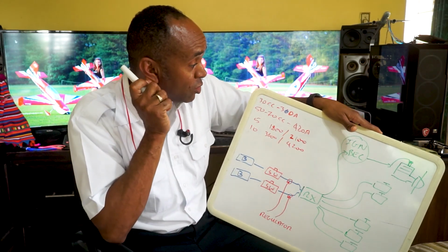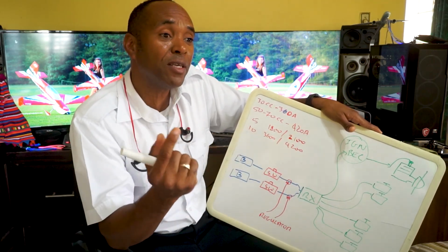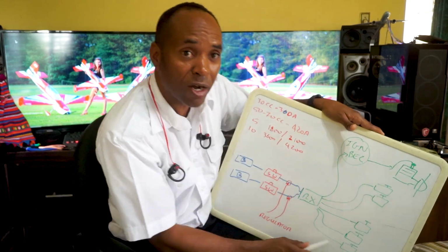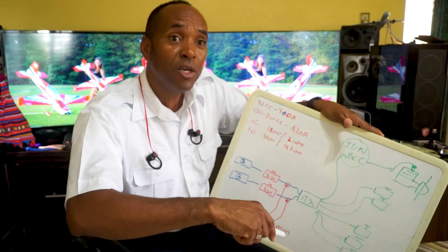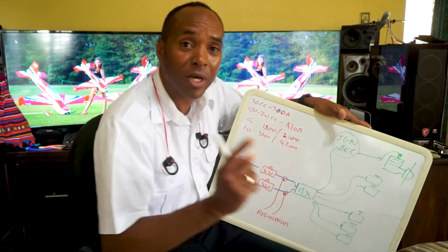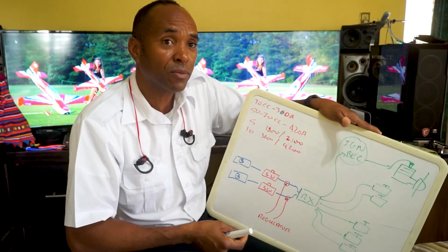Now the next thing is that not only is this the average amps per flight, but you have a thing called peak amperage. When all servos are stalled and everything is on the load, you're going to get a huge current spike. Every component in the system must be able to absorb that spike without burning out or without getting hot.